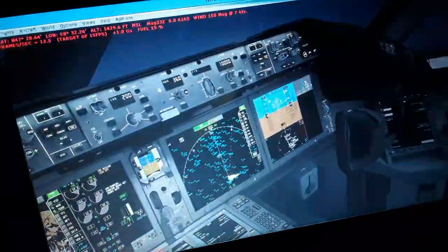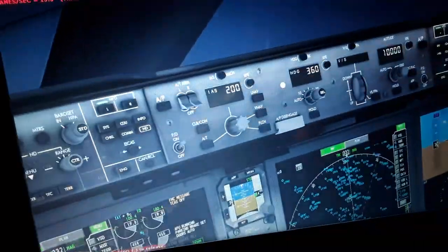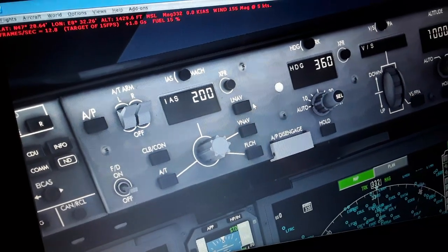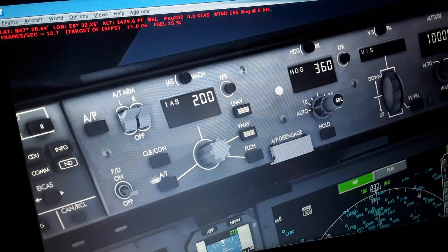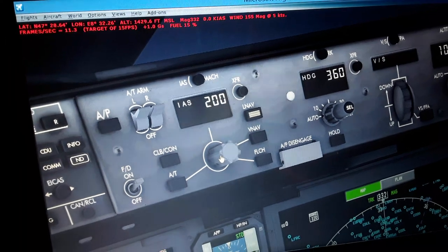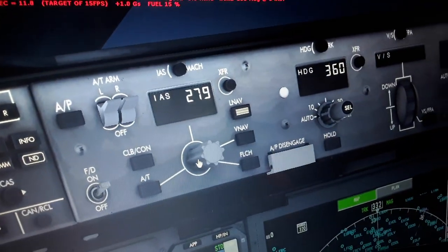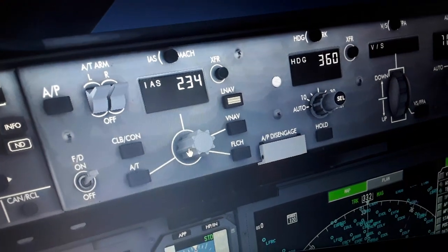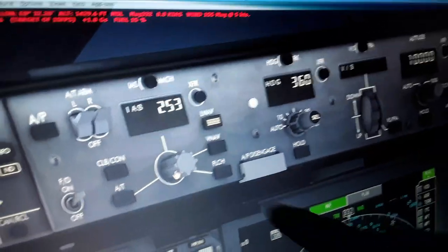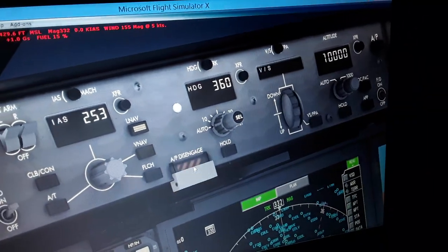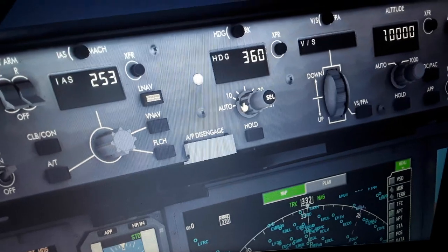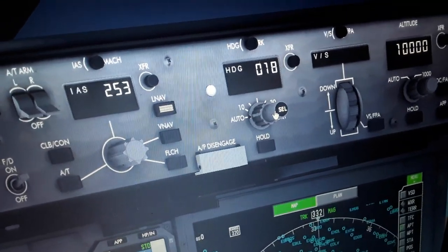Before going for flight, we need to set a couple of things over here. Autopilot engage, disengage switch, auto throttle, left and right, flight director on off. We cannot arm anything with the flight director off. We always need the flight director on. So the airspeed here, we're going to set the airspeed like 253. We have flight level change, climb continuous, auto throttle, autopilot disengage like this, auto throttle off, left and right, bank angle in flight, heading, we're going to use magnetic north heading, 136 degrees.